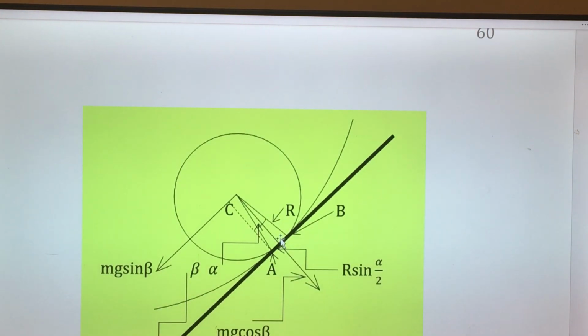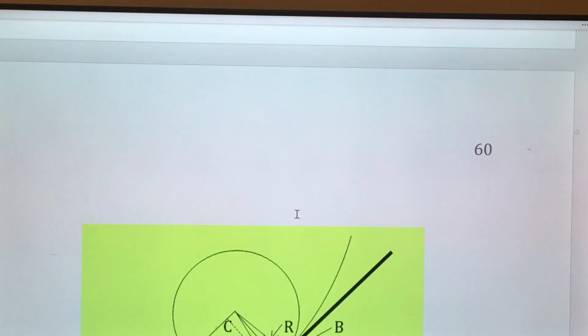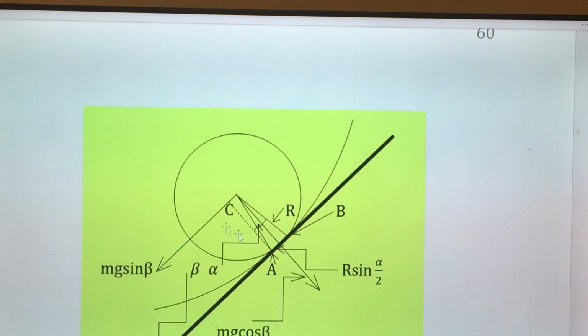Okay, now what is alpha? In reality, when we have a circular cross section, then a small area gets in touch with the inclined plane, causing a small circular area of radius a. If it's a sphere, we will consider a ball, a spherical body, rolling down an inclined plane. So we have a small circular area. Depending upon the elasticity of the two materials in contact with each other, there will be a small radius, in millimeters or in centimeters, of a circle of radius A in contact on both surfaces. Okay, so this will be A.